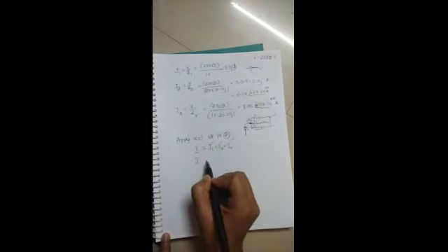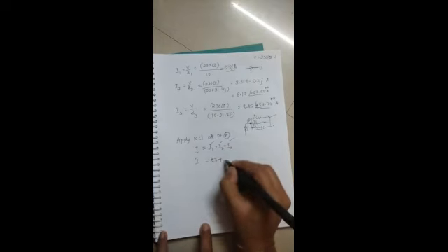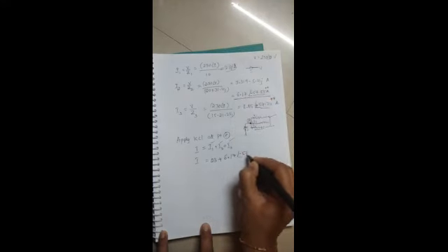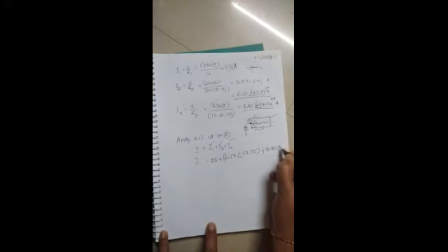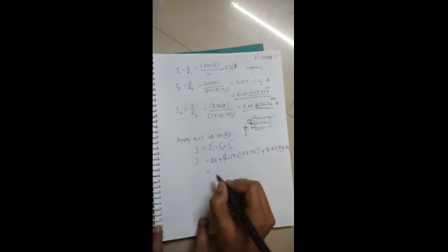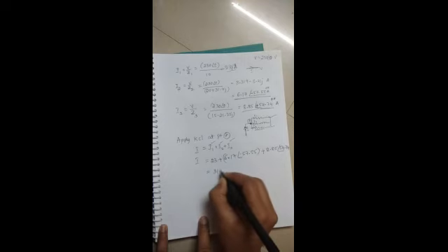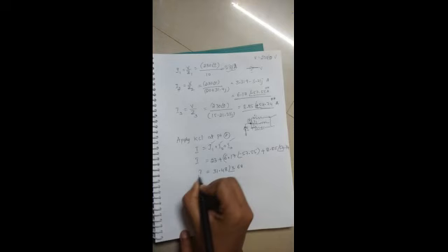Since you have calculated I1, I2 and I3, the total current is I equal to 23 amperes plus I2, which is 6.17 at an angle minus 57.55 amperes, taken in brackets, plus I3, which is 8.85 at an angle plus 54.74. The total current is equal to 31.48 at an angle 3.68. Now this is the total current, so the second task is also completed.